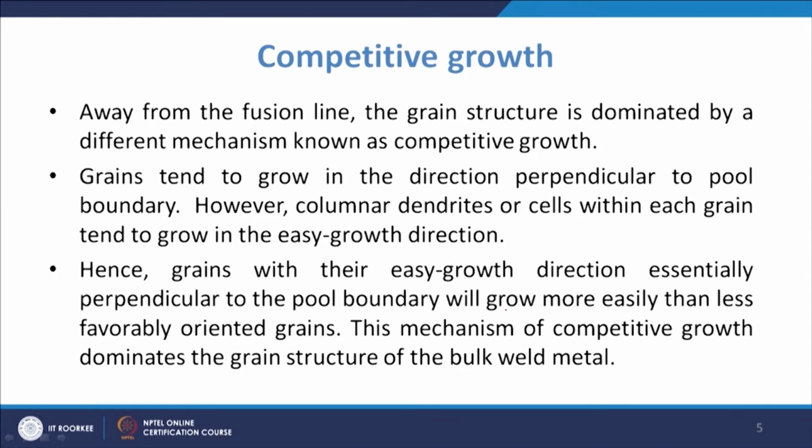Others will be pinched off, because they try to grow in their easy growth direction but it is not perpendicular to the primary heat flow direction. So certain grains will be pinched off, and the grains with that orientation will grow primarily columnarly.